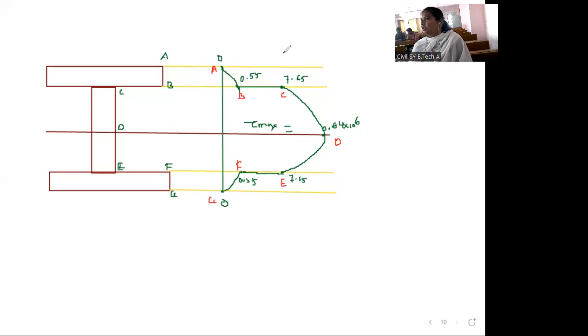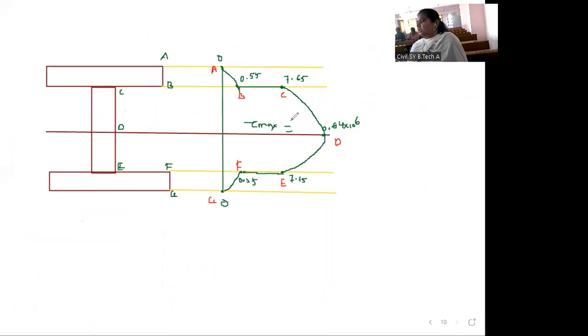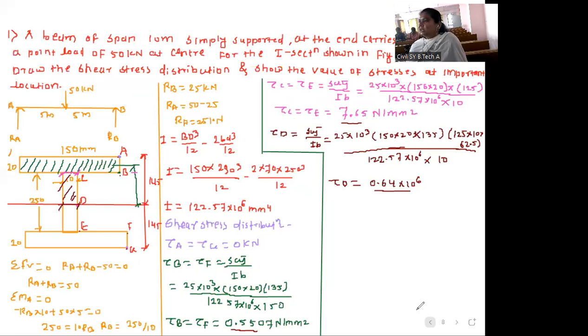Likewise, you have to draw shear stress distribution diagram. Okay, so first you have to find out moment of inertia. After that, shear stress at each and every point. And once you got shear stress values, then you have to draw the shear stress diagram. Take screenshots.